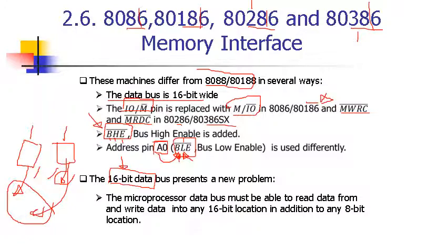So you make use of your wider data bus of 16 bits, bringing in or taking out 16 bits in one clock cycle, while you do this in 2 clock cycles if your data bus is only 8 bit.